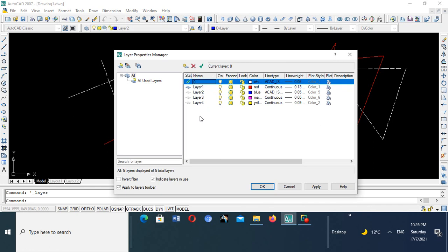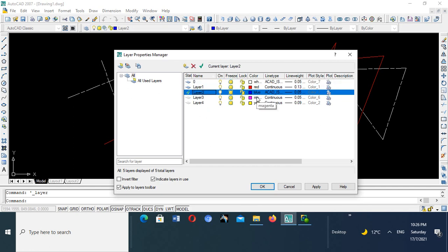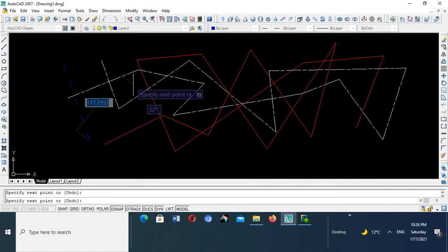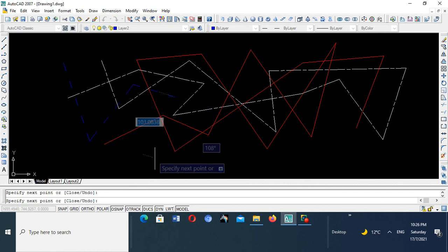And then that addition of layers, you can make your drawing have different sections of the drawing, the different color. So check, now we go layer 2, double click it, it's blue. Check now, every line that should come now is gonna be blue, and it's gonna be of that line type.